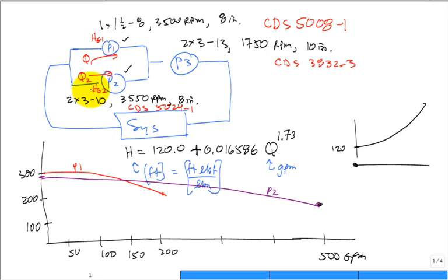Yeah, it's true, right? But then the net flow by an equivalent combined pump that is physically in parallel would simply have the sum of the Q's for each head. So the combined would take this red curve and this purple curve and really not change their height, but make it stretch out further. Make sense?